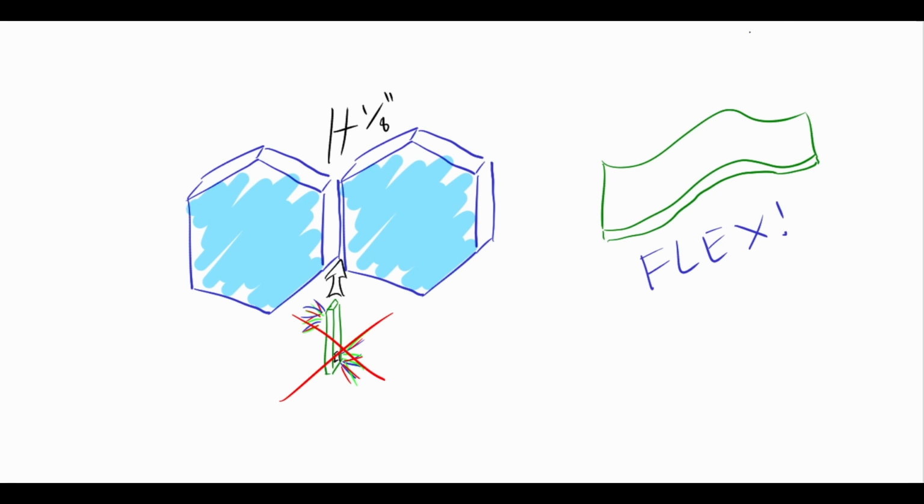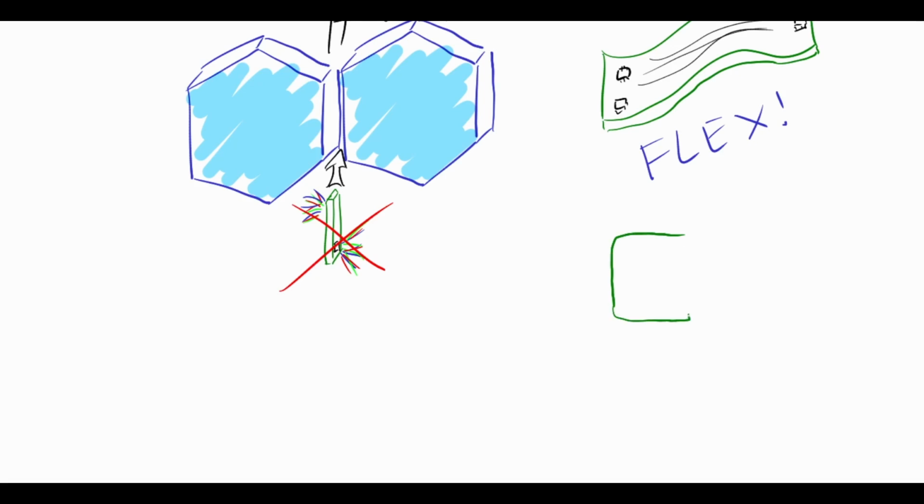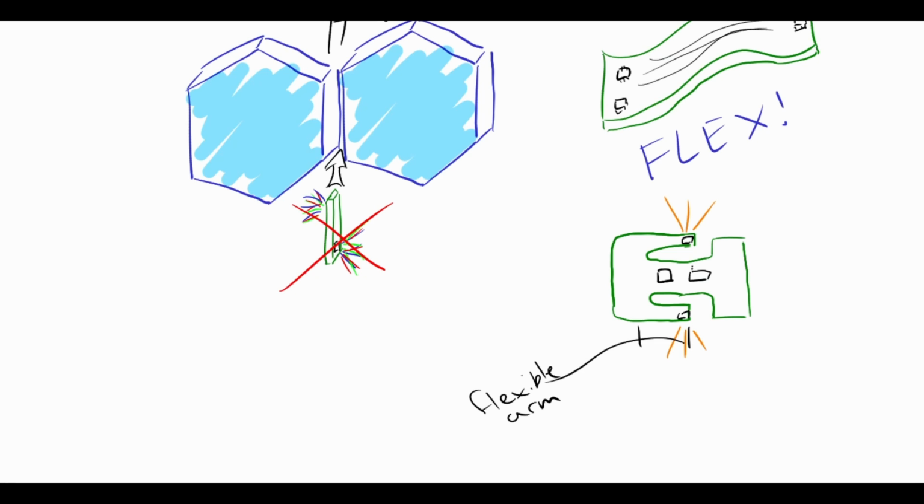I settled on flexible PCBs. My favorite low-volume vendor, OSH Park, offers these for $10 per square inch for 3 copies of a board, meaning they could be affordable as long as I keep them small. I may explore even cheaper options for PCB fabrication for the full build. With a flex PCB, I can have a large area parallel to the tiles where the bulk of the components will go. Then I'll have the LEDs out on these little arms. I'll simply flex the arms to 90 degrees, slide them in the space between tiles, and glue them in place.